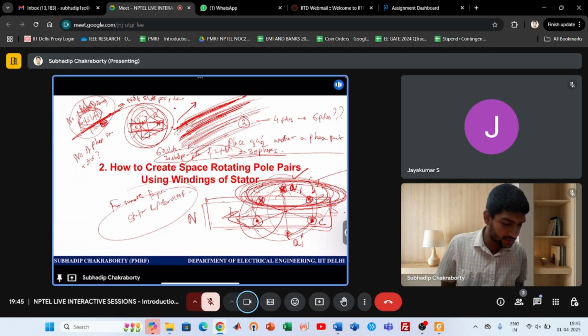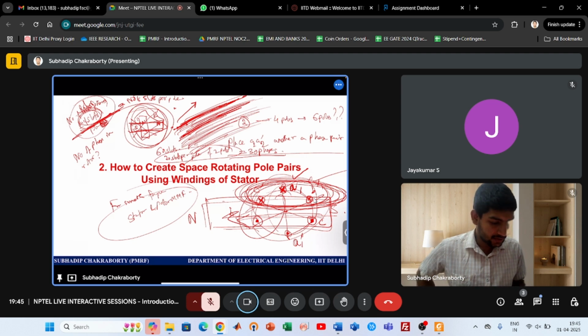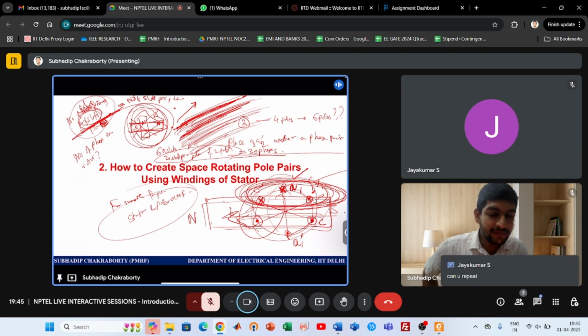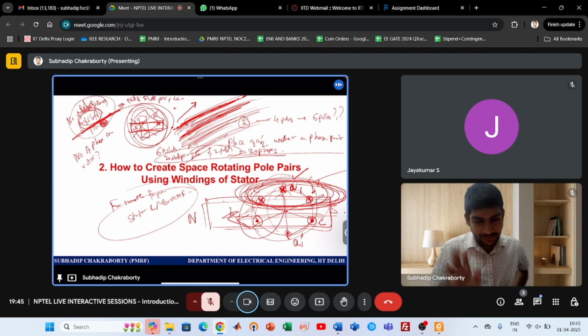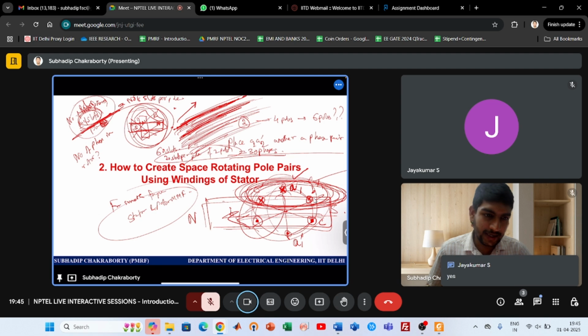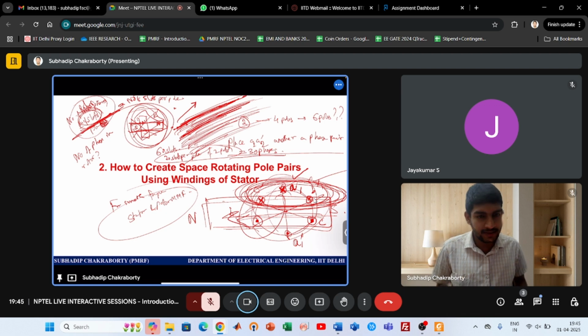This you will not find in many books, but it is a concept that many people don't know. And I am here to tell you the things that you don't know, and it will give you interest. So what I was telling is the number of phases in the stator and rotor. Up to here you understand that for smooth rotation, the general theory of AC machines mandates that the stator and rotor poles should be stationary in space with respect to each other. And for that, the number of stator and rotor poles should be equal. Otherwise, you cannot get smooth torque, right?